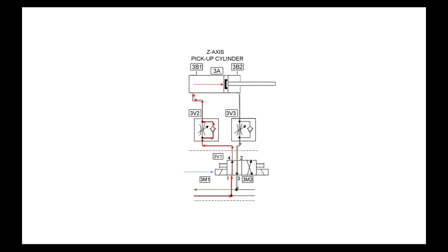Now, sometimes it does create a little pressure. Sometimes if the check valve is not going to be oriented right, then they'll put a spring up there to make sure the check valve closes. If it's got a spring in the check valve, there might be a little flow through there, but 99% is still going to go through the check valve. So it's not going to affect the flow. That makes sense? So y'all understand the difference between meter in and meter out.